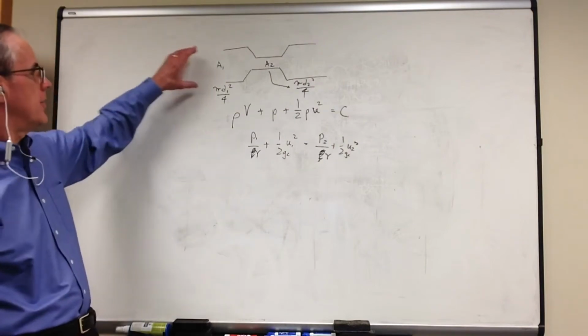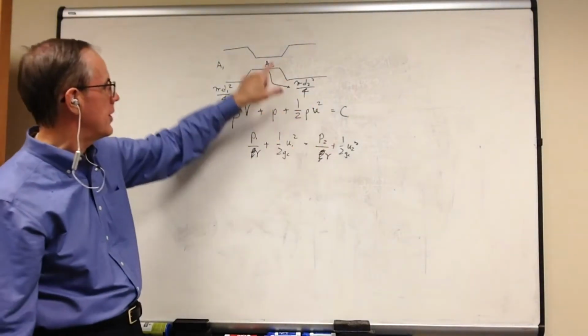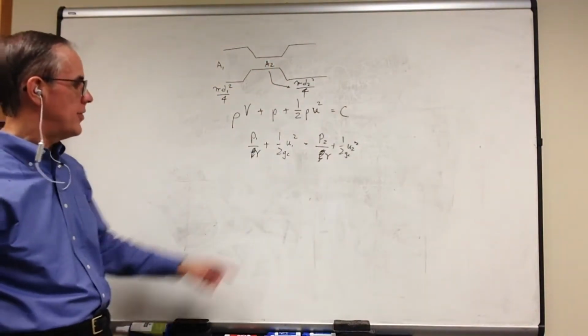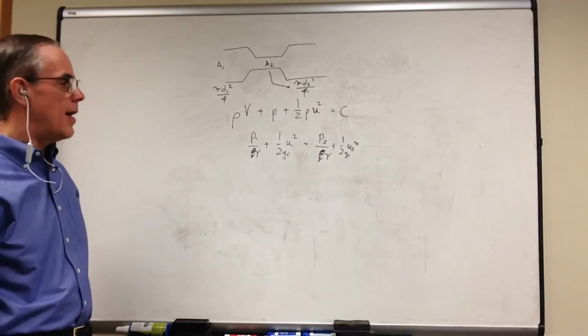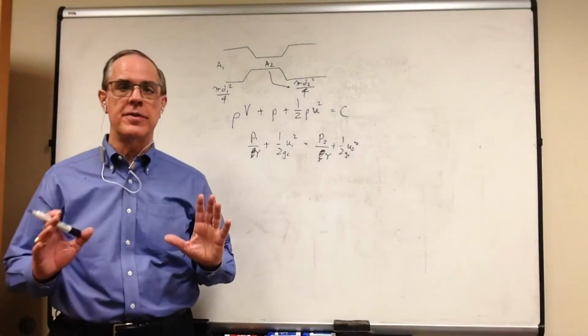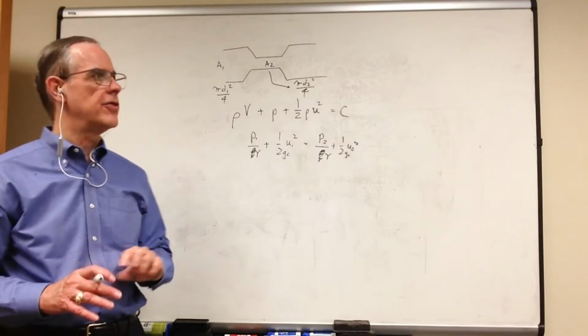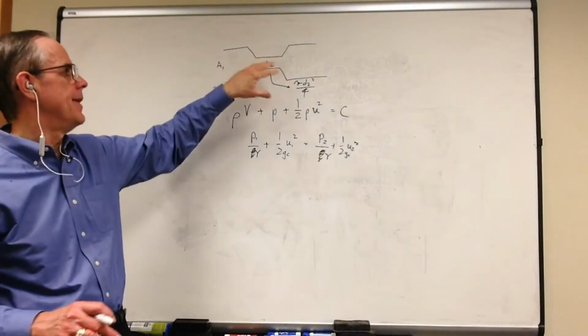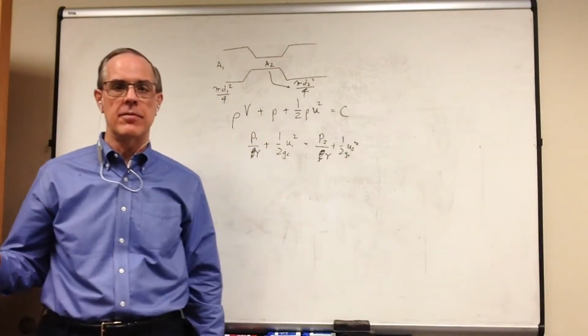If I have a constant flow, the velocity from u1 to u2 will increase, and the equation tells me the pressure will drop if I measure a pressure difference. The problem is that Bernoulli's equation breaks down a little bit because it doesn't take into account losses due to turbulence and flow losses, shear losses due to the viscosity and all that.